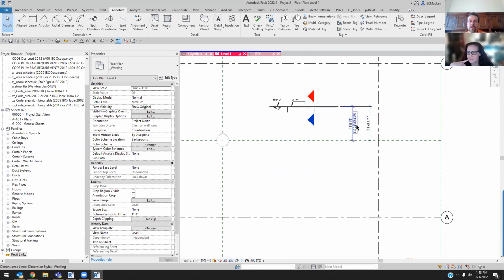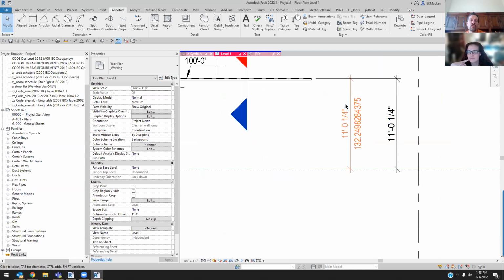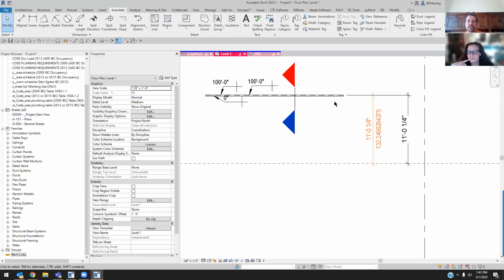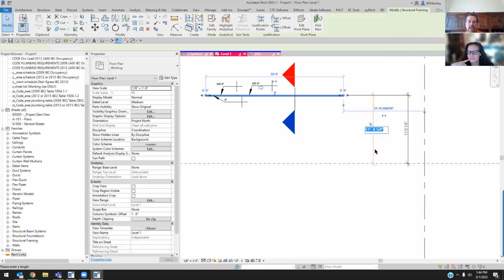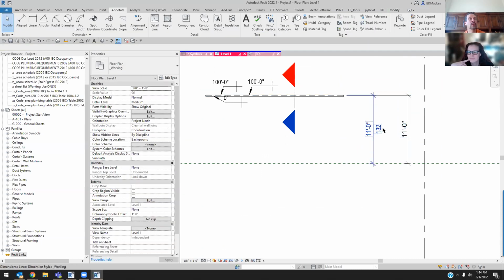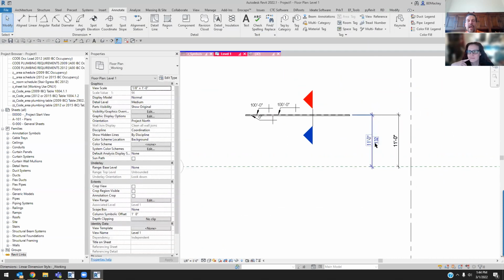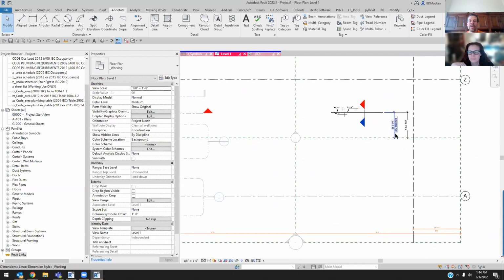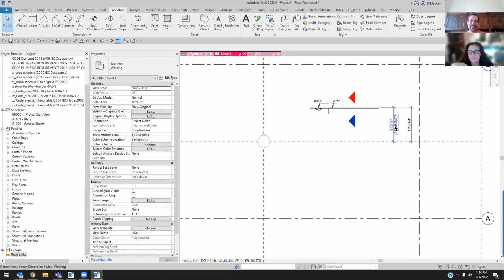So yes, I do this. This is the only dimension string I use. And people laugh at me going, why do you care about this? What's the big deal? Well, if I do this and I make it correct, I don't see those numbers. The number goes short, right? And I purposely have this suppressing trailing zeros. So that way, when it is bad, I can just be cruising around a project going, why the hell do I have a very long dimension string?